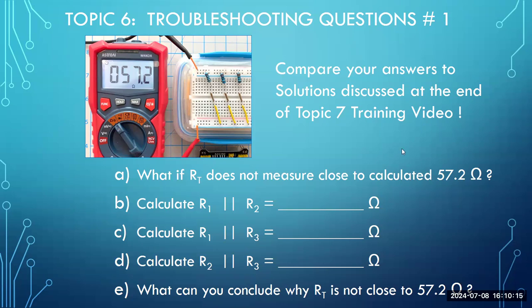What could be a problem? What would be some scenarios that would cause you not to be able to measure 57.2 ohms? Suppose you measure some other kind of ohms, like 100 ohms, you measure 220, suppose you measure 500 ohms. What are some of the possibilities?